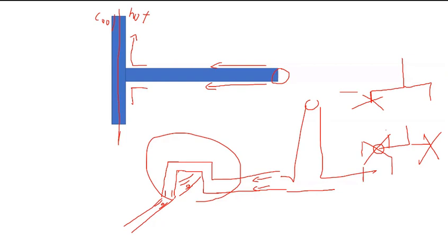Okay, the next one: a stress mark happens because of the sharp edge on the part or any other reasons. I would say in some cases, yes, the sharp edge on the part will cause the stress mark. But the case I shared in case one is more caused by the temperatures.